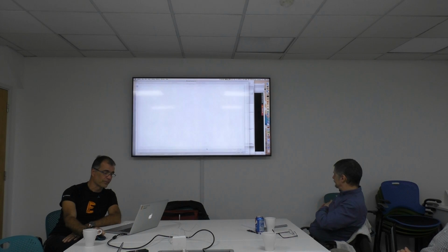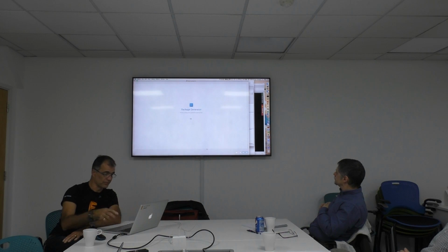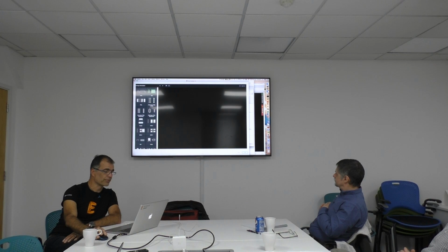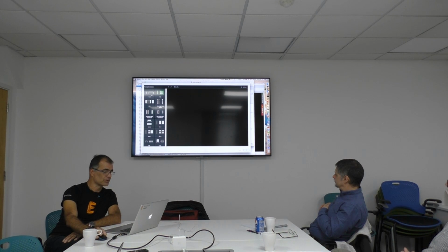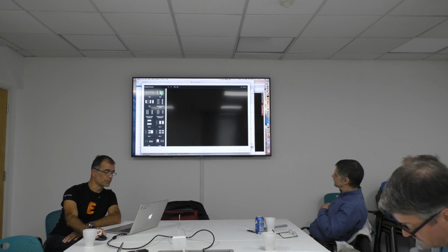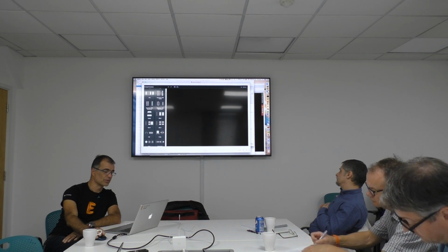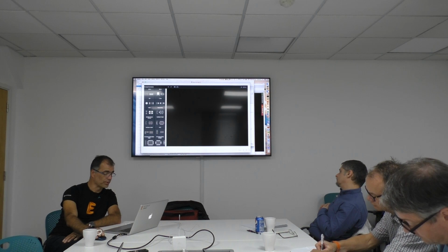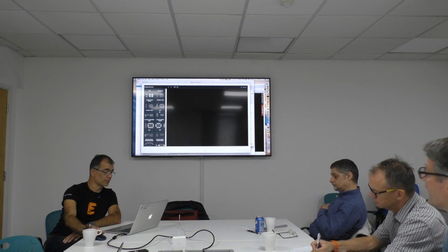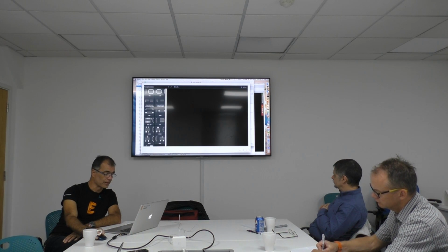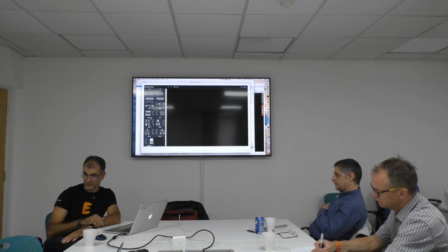I say I want to have a 3D package plus footprint for a component. Normally you would have a data sheet. Okay, I have to look for a data sheet. But just here in advance you see we have different options what you can do. You can also create through-hole components, axial things, BGAs, chips, chip arrays, so different kinds of components. And that's something we are constantly improving and adding more stuff to it, because there are so many different components. It's not so easy to have everything at once.